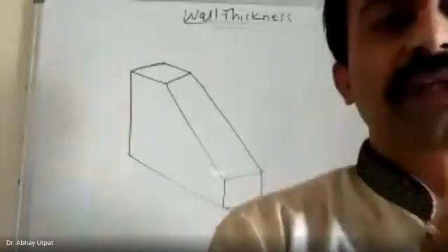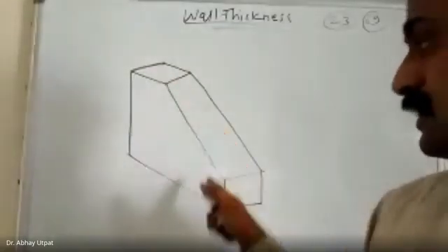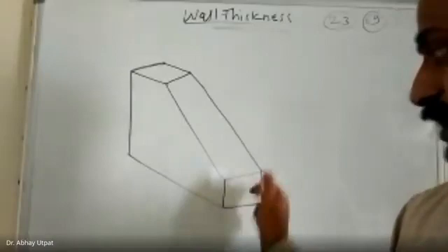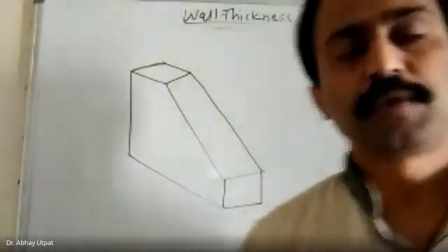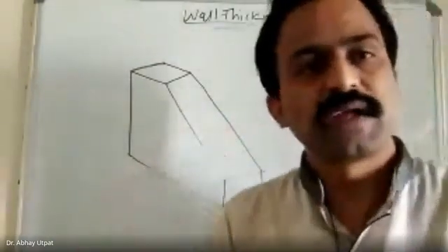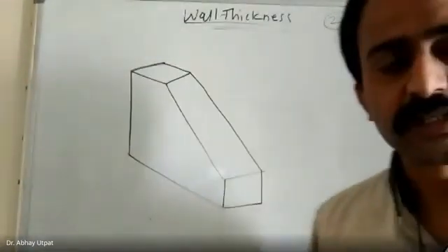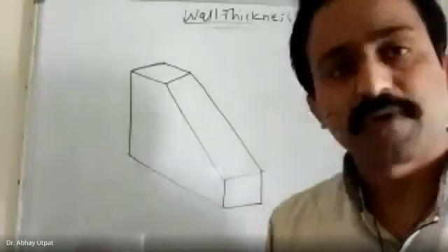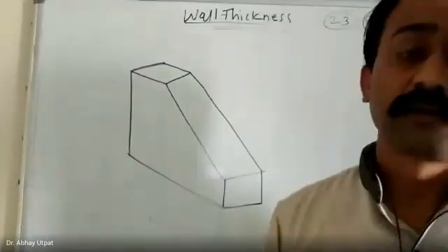Please answer this question. So one figure is in front of you. I have drawn it on the board. This is the plastic component. There is a dimension limitation constraint. Without changing the outer dimension, how can you reduce the thickness of this component? Because with this high thickness, you can't get this product easily because of the solidification problem. Assume that after 3-4 months you are working in an industry and you are facing such a problem. How can you suggest as a design engineer? Tell.